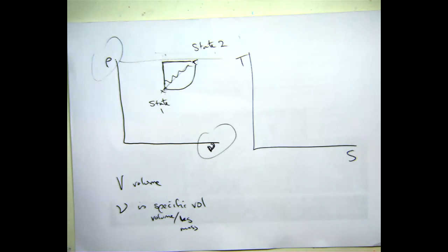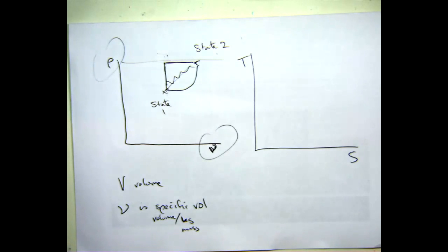Provided the two axes are independent, drawing a dot on the axes defines the state of the problem. Drawing two dots gives me initial and final conditions. I can analyze the change in energy. Given two dots and a line, I can then talk about the process to get from 1 to 2. So we use these maps all the time. Our two favourites are the ones that I've drawn down, which are pressure versus volume and temperature versus entropy. We'll do them a lot.